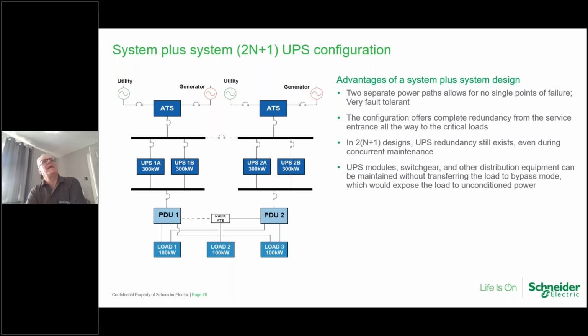But the other interesting thing here is that you can bus couple, even on the input side, so that it makes this power, or the generators, available to either side in the event of something catastrophic happening downstream and you can't use it.